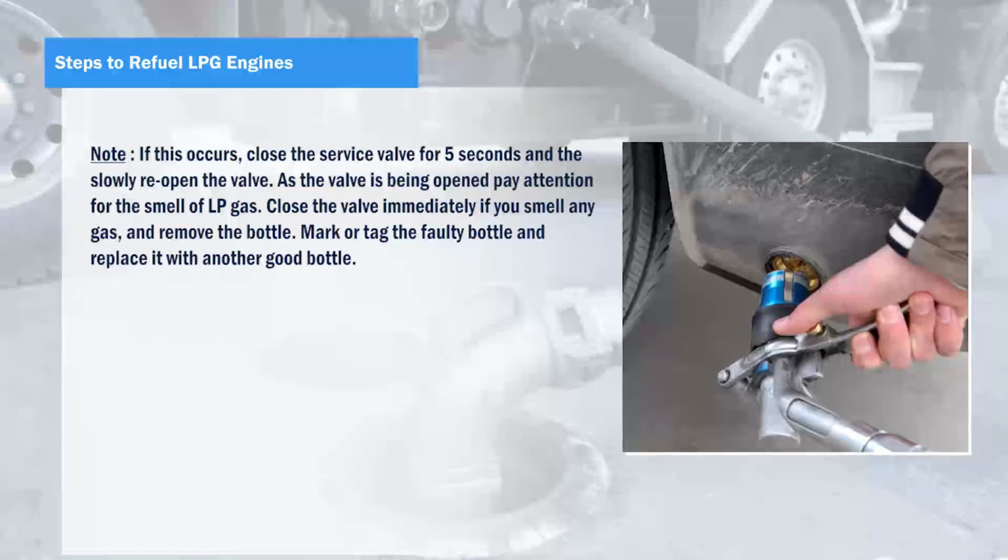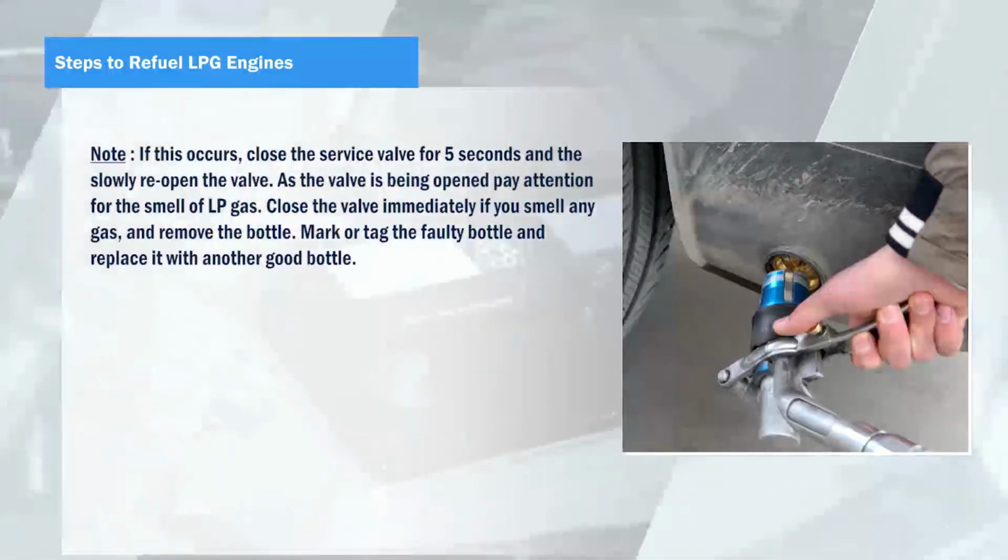As the valve is being opened, pay attention for the smell of LP gas. Close the valve immediately if you smell any gas and remove the bottle. Mark or tag the faulty bottle and replace it with another good bottle.